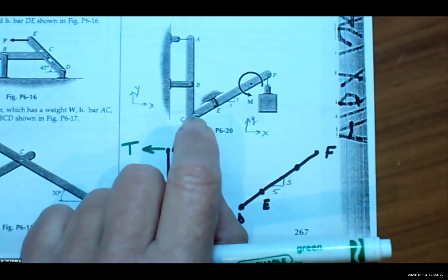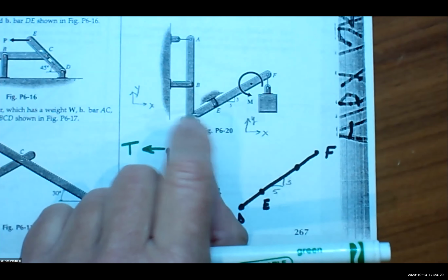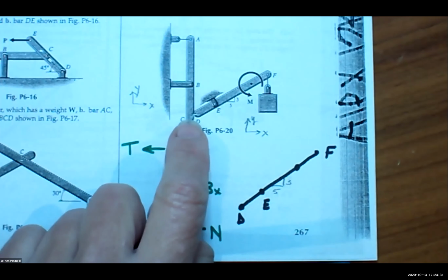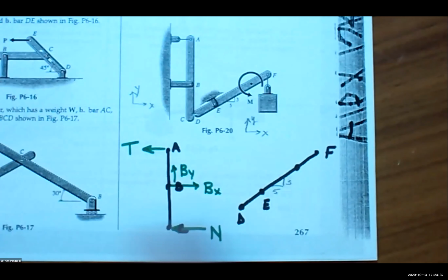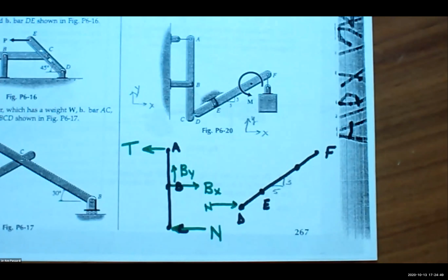I can't tell, but I think the only contact is just on C. Correct. The only thing that's happening at D and C is that they're touching each other. So on body ABC, I drew the normal from D going to the left. So what do I need to do at point D? Draw the normal coming from the left. It's equal and opposite, right?